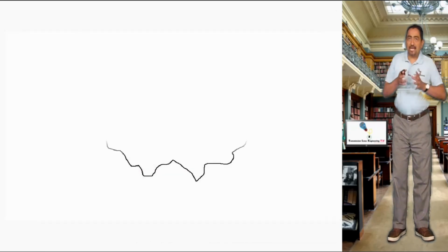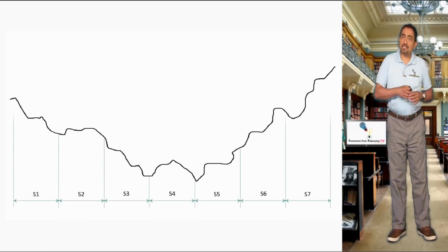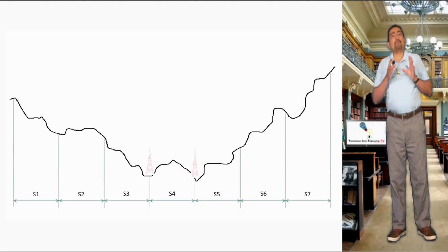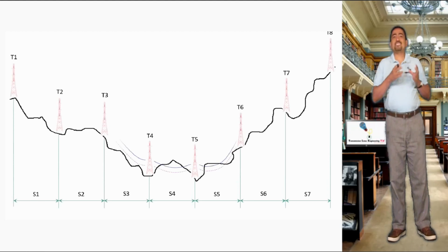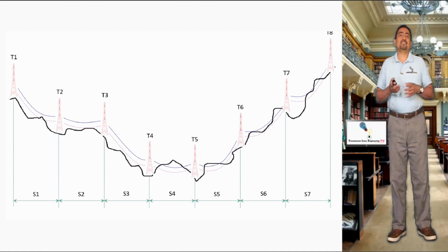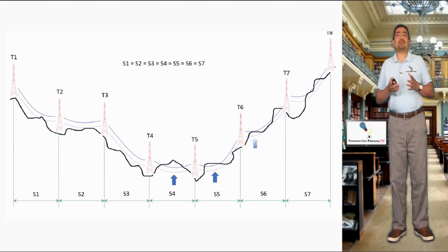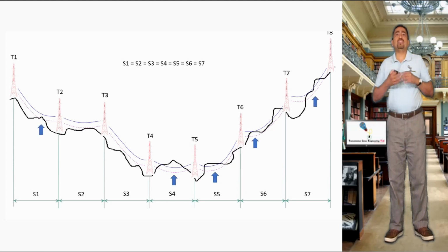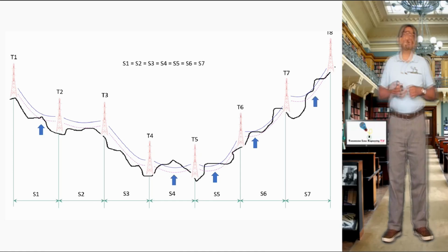First, it began with the criteria of locating the structures in a uniform manner, that is, maintaining a uniform span. However, the designers realized that for the same curvature of the cable catenary, it was not possible to maintain this uniformity since it presented ground clearance problems.